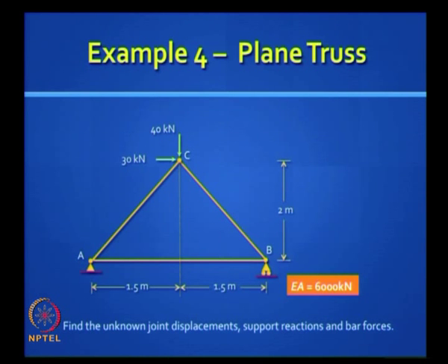But we do not want to do that method, we want to do it the hard way. We want to do the stiffness method, because did you know that the computer will only do by the stiffness method. Let us say you had a nice transmission line tower, spaced structure, it is mostly statically determinate, the indeterminacy is very low. So the standard software will choose to solve 120 equations simultaneously than do it by the force method, because you know that is how you program it, right. So this is a much smaller truss, very easy to do.